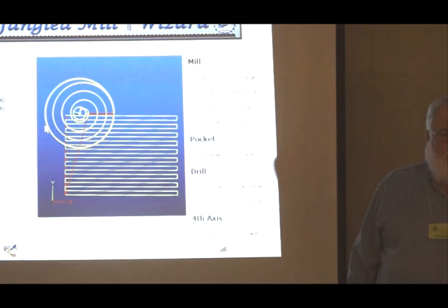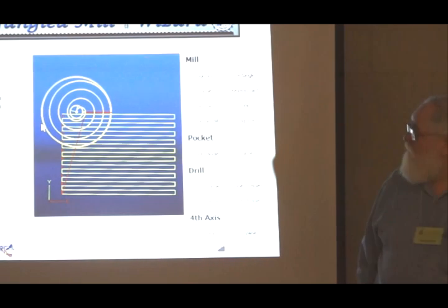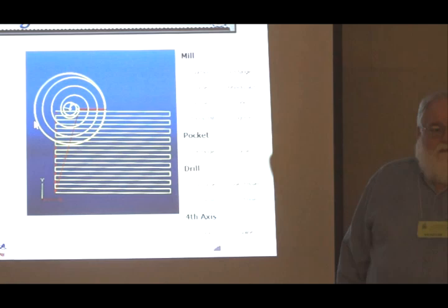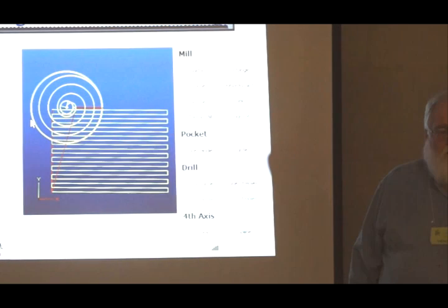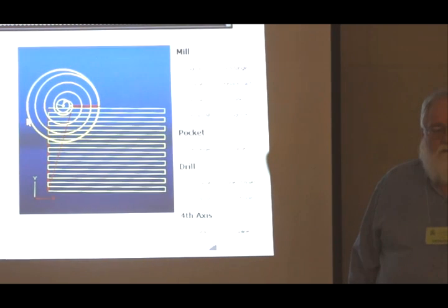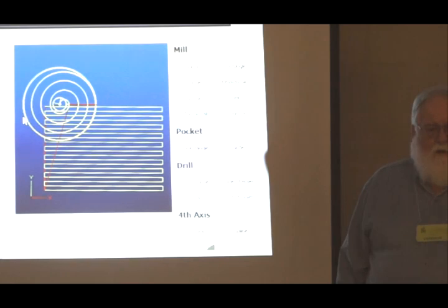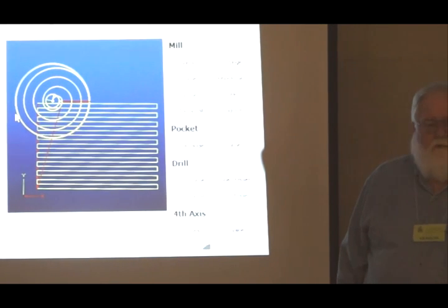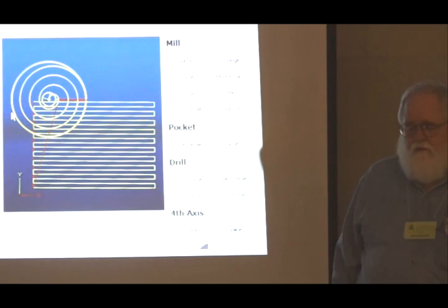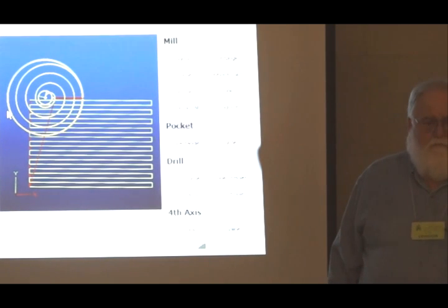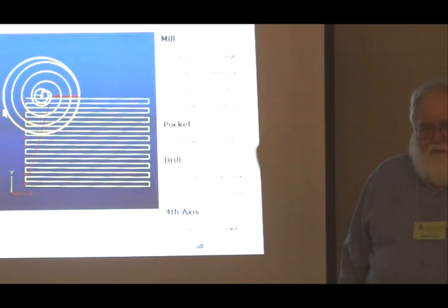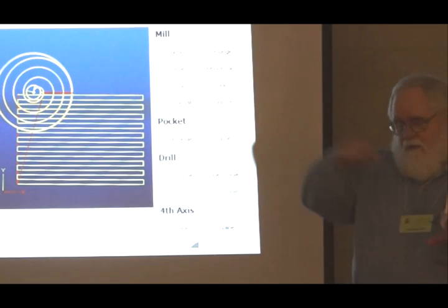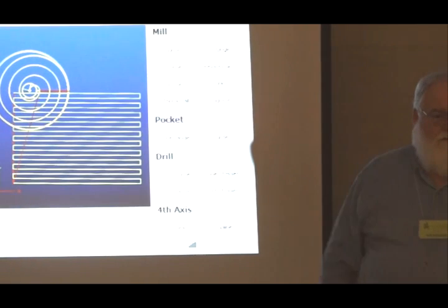Oh, you want to cut a circle, not a pocket? Yeah, a disc. I needed a 5-inch disc, but if you went with a 1/2-inch tool, would that already calculate that offset of the tool? Sure, it takes care of all that. It's not based on the center of the tool. It figures out what diameter tool and it makes the cut. The numbers you enter are the numbers of the finished part. So if you want a 5-inch disc, you program it for a 5-inch disc. It'll calculate how far outside of that the tool should go.